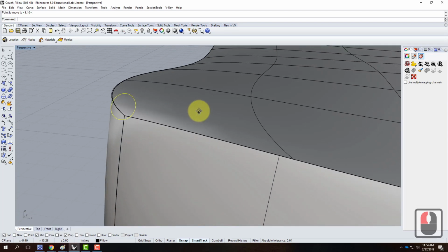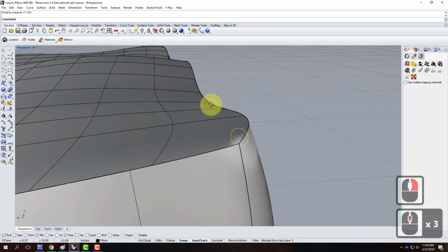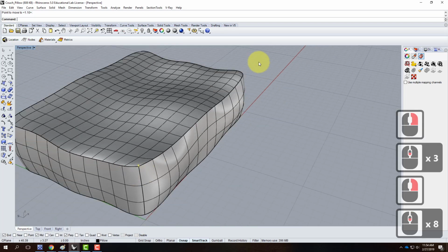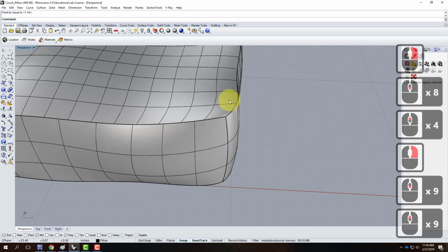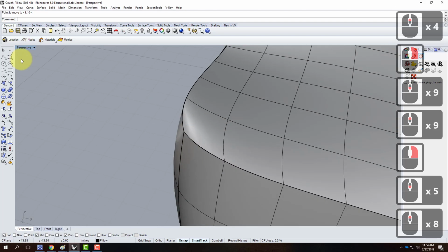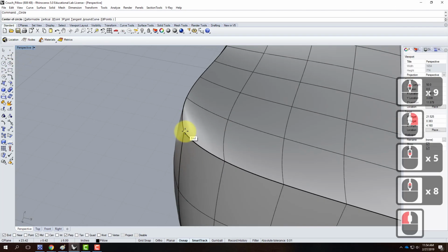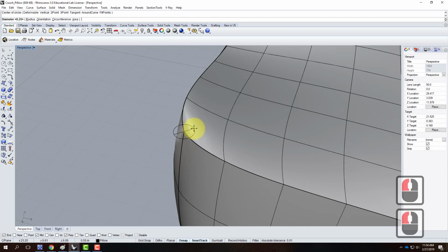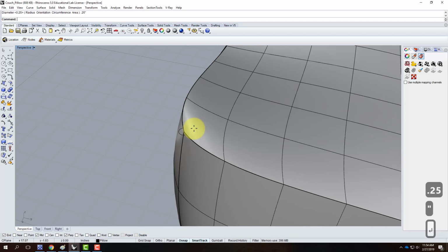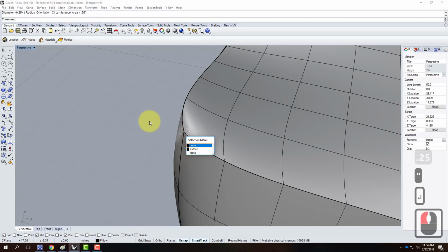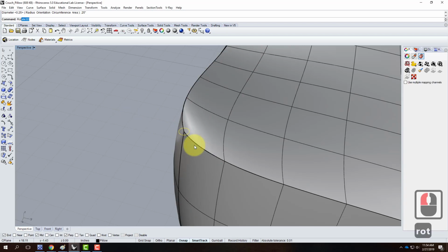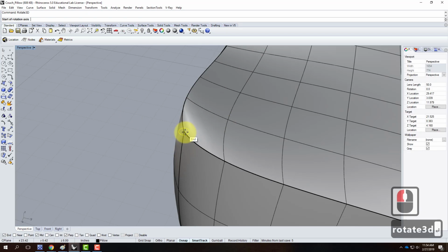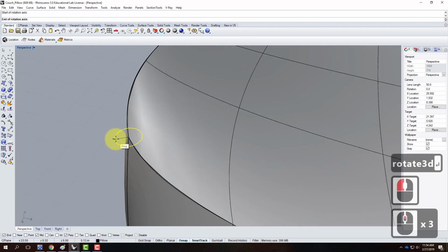Did you do the 45-degree rotation again? Sure, I'll do one over on the other corner just so you can see me do it again. No problem. So I'm going to do the circle. I'll snap right to that corner. I'm in diameter mode, and I'll do a diameter of 1/4 of an inch, so 0.25 inches. There it is. This then needs to rotate so that it stands up at 45 degrees. When I do the rotate 3D, I can guess at where that 45 degree is. I can come out here and snap for that.